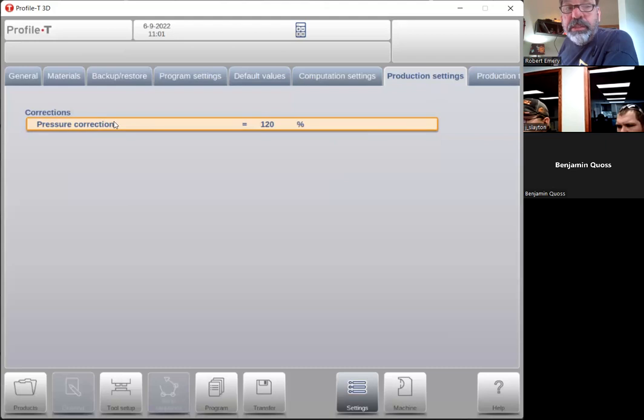The production is just about the valve. Again, it's airforming. So what we're saying is, whatever you calculated to do the airform, give me 20% more. Because with airform, I'm going to some dimension, really, even though I told it an angle, it calculated to some position, and I just need to get there. Whether I had 10 tons programmed in there or 50, it's still going to the same position.